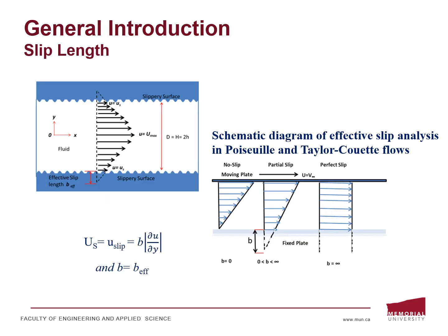After applying the superhydrophobic coating on the surface, an air layer is trapped between the surface and the fluid. This layer works as a lubricant as a result of the different viscosity. This reduces the shear stress as the fluid flows over the air and creates slip velocity. Slip length is another parameter used to describe the surface slippage velocity.